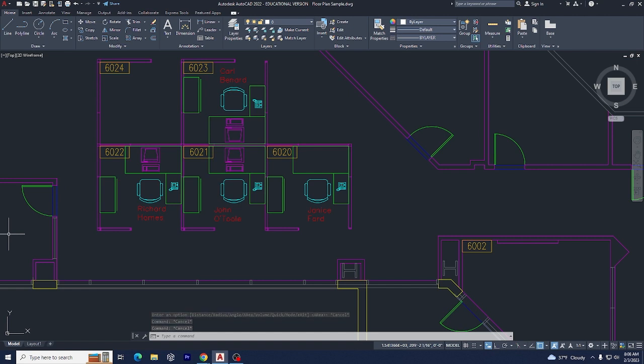Two inquiry commands you are most likely to use object snap with are ID and measure geom. The ID command reports the coordinate value of any point you select with the cursor. So any point, if I select this point right here, it gives me the ID. Do it again at that point. There's my X, Y, and Z, and since this is a drawing in 2D, there'll be no Z on any of them, but this can tell you exactly where every point is on this drawing.